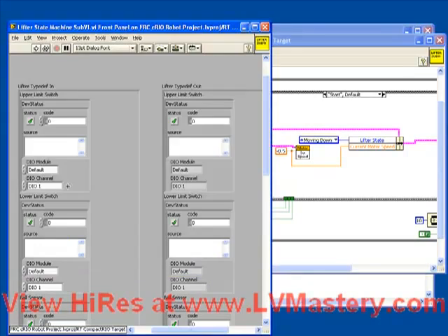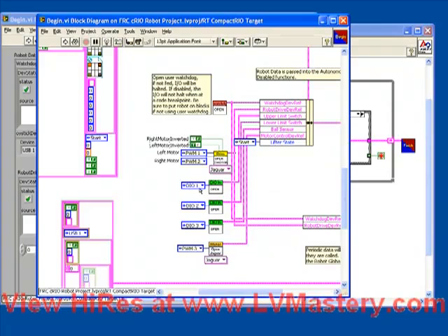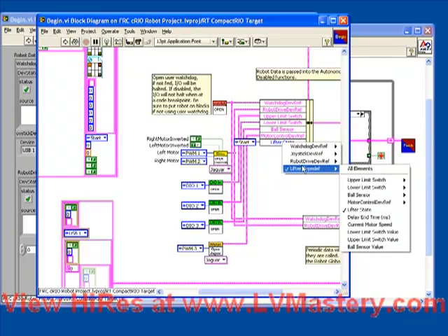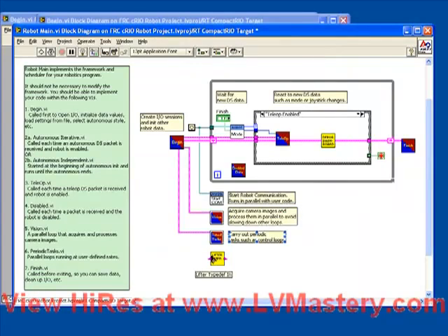And the other really important item is to make sure that we wire up the parameters which we initialized in the begin VI. Let's review inside the begin VI all of the data which we initialized, the opening of the 3 digital inputs and the motor. All that information is placed in the lifter type def. But that lifter type def is actually inside the robot data. So instead of having the lifter type def as the input here, we're going to modify this so that it takes all of the robot data in.